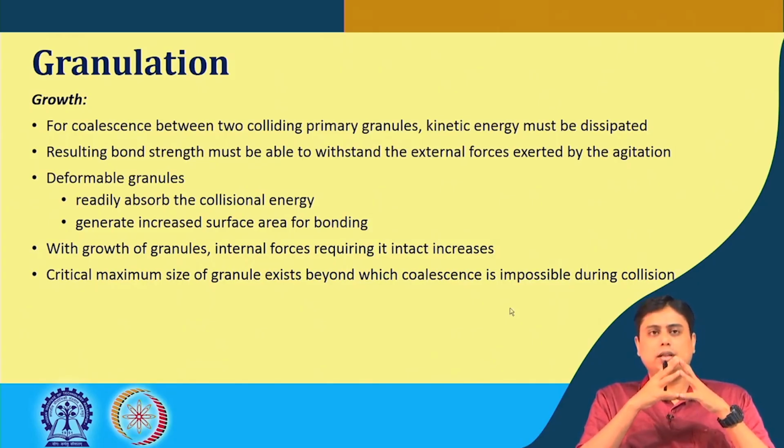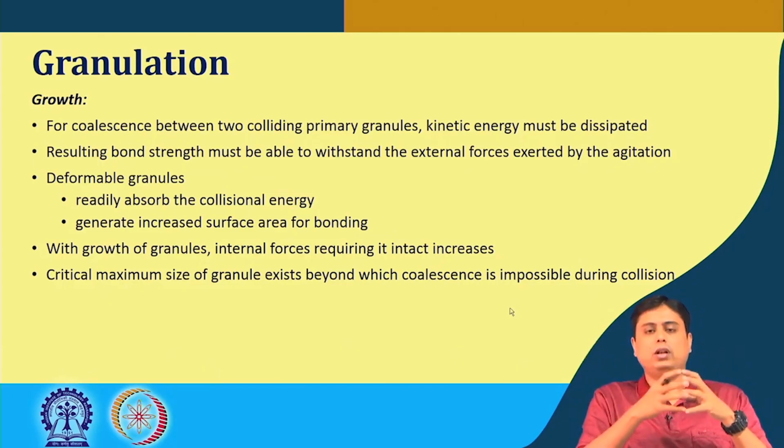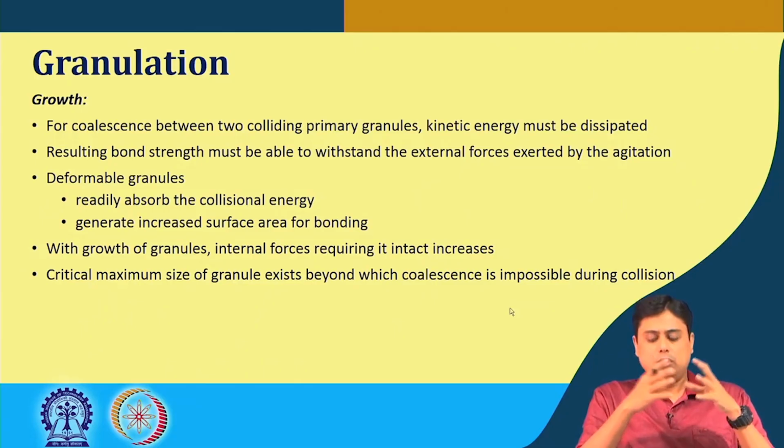Now, researchers have shown that there is a critical maximum size of the granule, beyond which coalescence is impossible during the collision. So, not all collisions result in coalescence. There is a maximum possible size, because this is essentially the interplay between the internal bond strength and the collisional energy. So, not all the collisions will have coalescence.